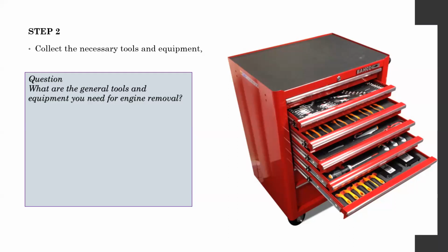So you need that, and you especially need the engine crank, or we call it the engine load lever. So we need the engine load lever, and in addition to that, any other things like supporting or jacks. Sometimes we actually need these things in case the space underneath the vehicle may not be enough. If it is an inline engine gearbox assembly, mostly for cars, this happens when the gearbox is longer.